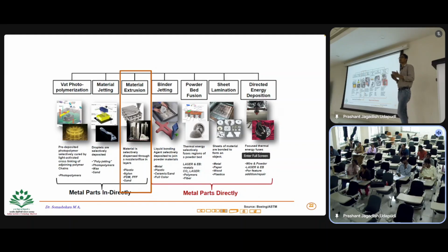Then you can manufacture a series of products, because you are printing one material and seeing the product come out of it, with a single material, or maybe you can combine different powders, but you get a component made with either a single material or a combined composition. But when you want to vary the composition gradually, or form different alloys within the structure, that may be a little difficult with powder bed fusion.